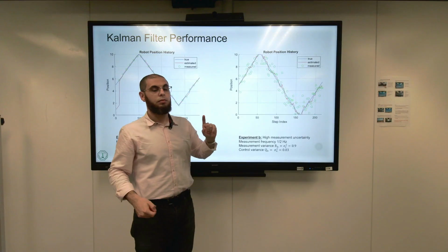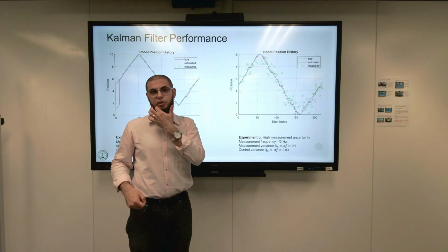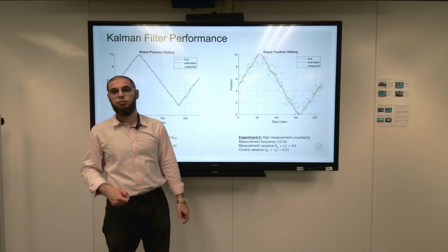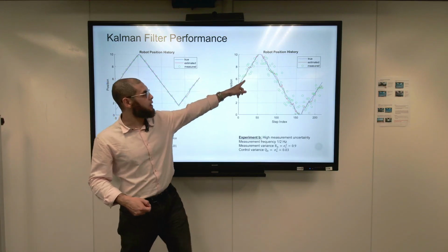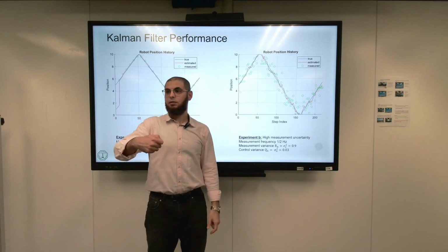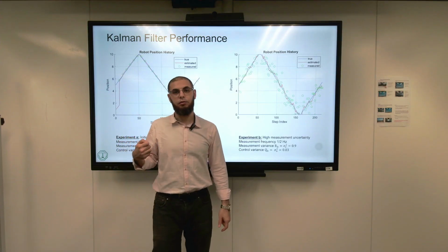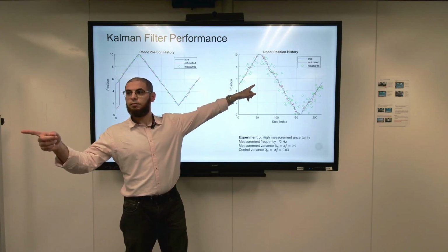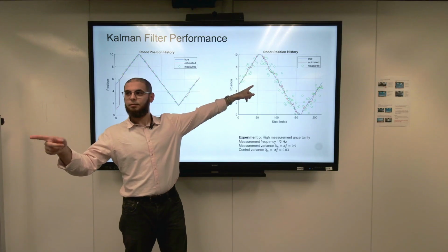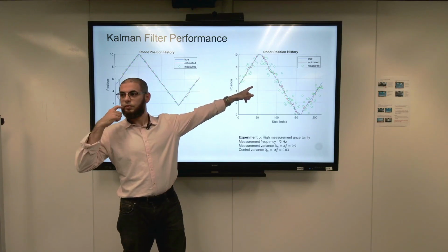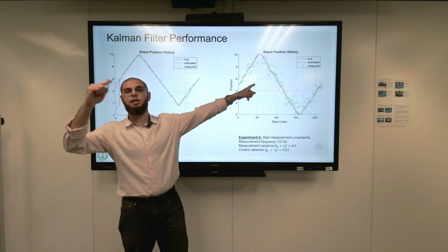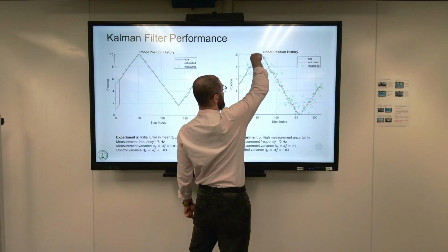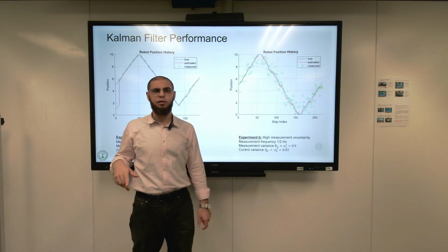In this scenario, we are not trusting the measurement very much. Why not? Why can you say here that we're not trusting the measurement? It's not following the whole. So what should you expect here for the red line if it was trusting the measurement more than the control, more than the state transition model? It will be more accurate and more similar to the measurement than the prediction, exactly. So actually it will be more fluctuating. You will see that the red curve should have had more noise. You had this, I think, in the assignment, right? Yes. You played around with it.